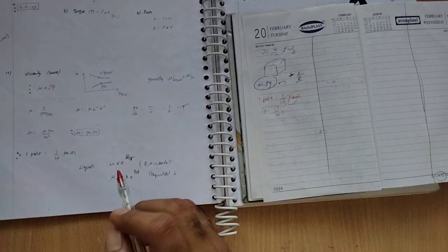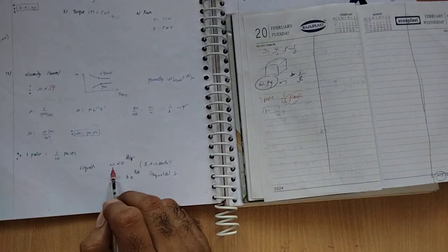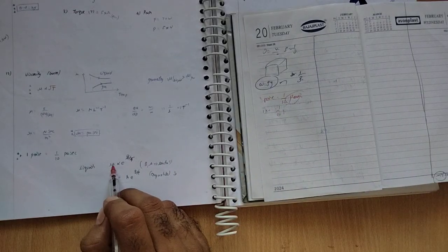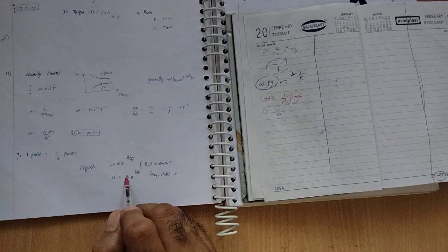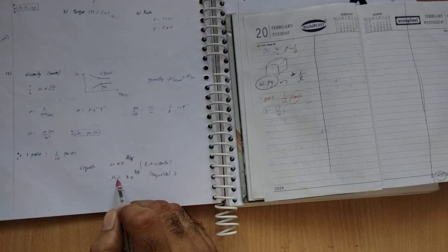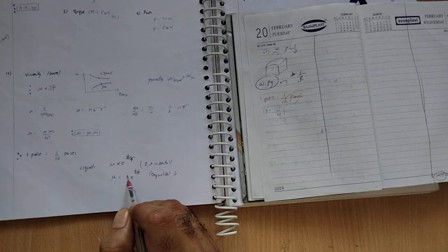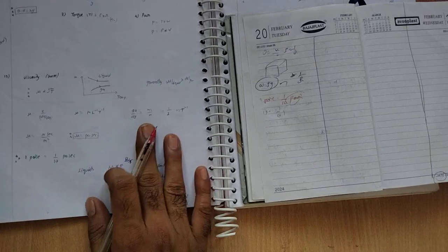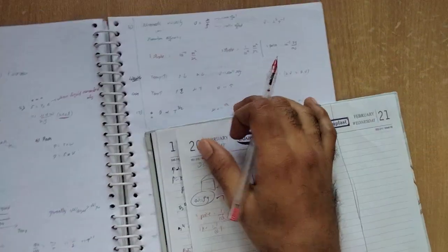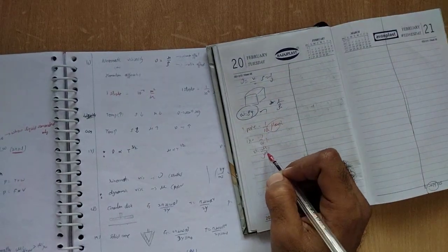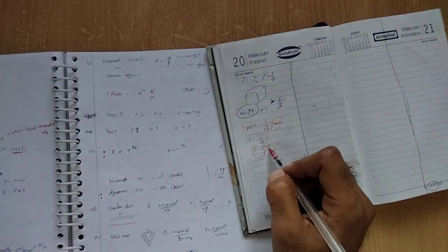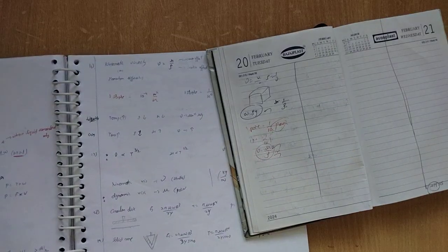So next, this is another thing. Generally for liquid, viscosity is directly proportional to exponential of b by T. We can put a constant and make it so. You can see viscosity sometimes varies exponentially. Next, kinematic viscosity: nu equal to viscosity divided by density. First one comes to viscous effect and inertial effect, both of the effects come.